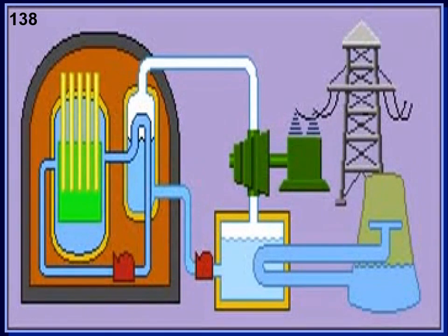In a pressurized water reactor, water is enclosed in 3 separate but interacting loops. In loop 1, water becomes intensely hot as it absorbs heat from the energy of nuclear fission. But because it is under very high pressure, the water doesn't boil and remains a liquid. Pipes from loop 1 wind through a steam generator tank that is part of a second, lower pressure water loop.